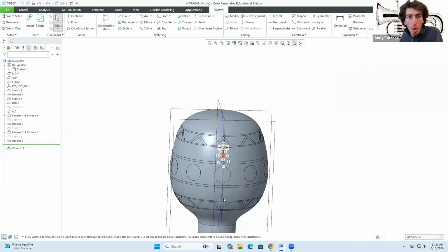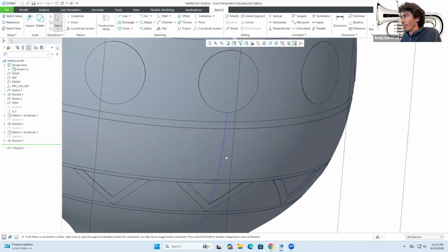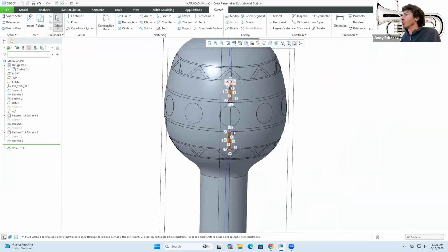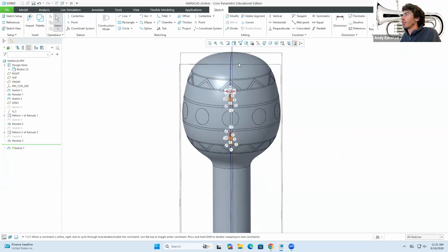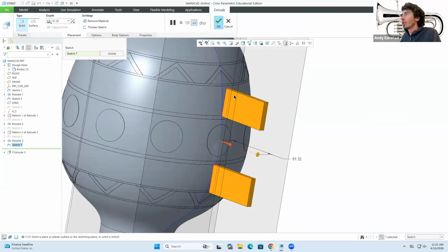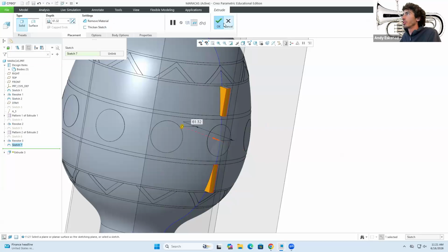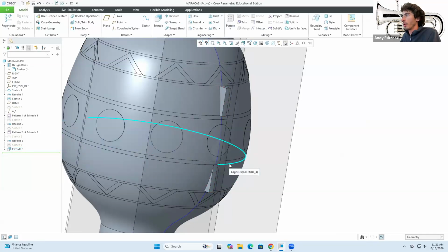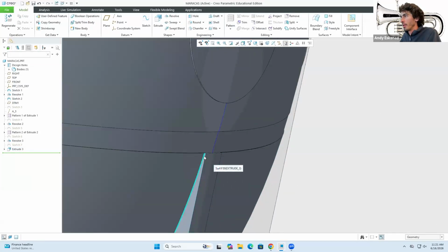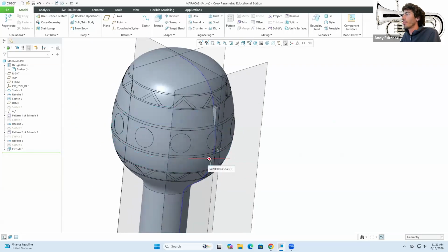And notice that I'm not quite mirroring things. It's not that I've created a plane here and I'm mirroring downwards, because this is not exactly a regular shape. So it wouldn't work as neatly. So I have that line, I go to OK, then construction, choose rectangle here again. All right, so it looks exactly there, good. So let's extrude in the opposite direction. Let's go here to OK, perfectly. You have the sufficient extrusion.